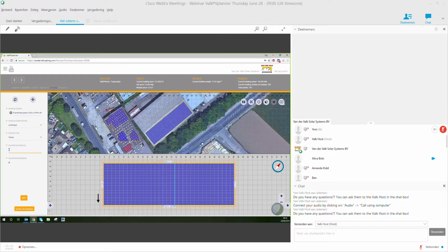You can add dilations if you want to. So for example, if we have a dilation after 3, you'll see that you then need a second dilation because you want to have a dilation here. This is then the maximum number of panels you can have side by side before you need another thermal expansion. Maybe we try and place it somewhere in the center, something like that. And if you change it to 0, then it's going to put it in the default place. So again, after the maximum number of coupled panels has been exceeded. We've got dilation in the columns as well. So you would now have 4 separate areas here.